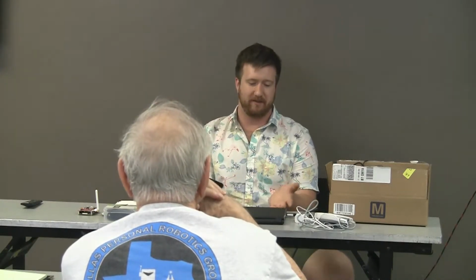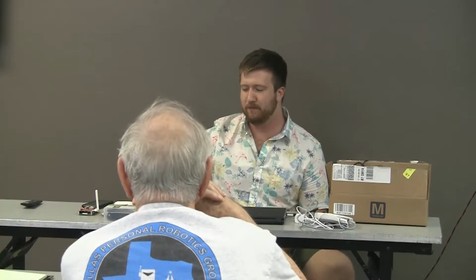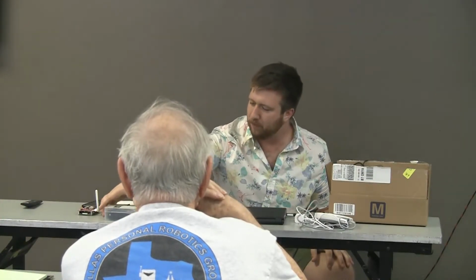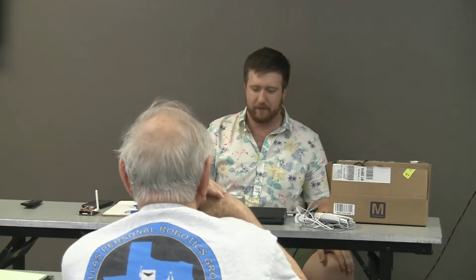So with Zigbee, in terms of how they communicate, with Bluetooth Low Energy, it's generally one-to-one, though there are ways to do more. With Zigbee, it's a network where there is a central one, and then client ones, where as soon as the command module sends a message, it is propagated through all of the lesser nodes from one to the other. It's called a flood pattern, where if you send it to one, it'll propagate it to all the ones it's connected to, until the message propagates to the entire network.